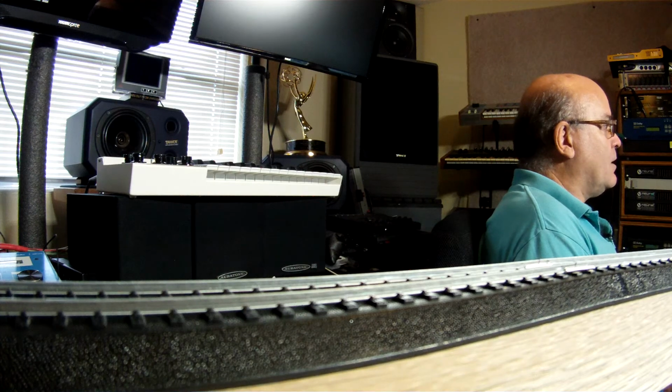Basically, you would wind up blowing a lot of speakers trying to make a speaker box work in that configuration. This is, of course, primarily a concern at very low frequencies or in a subwoofer cabinet, but is also a key factor in designing some full-range cabinets. High-frequency components like tweeters typically have a free air resonance point as well, but since most components of that type are essentially enclosed within their own enclosure, they are not terribly affected by the overall speaker cabinet's resonance of itself.